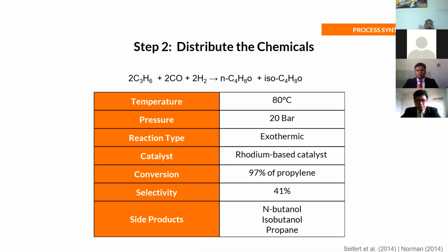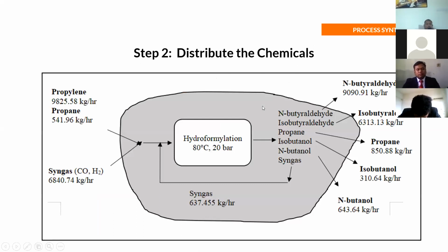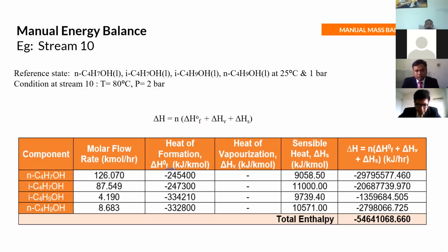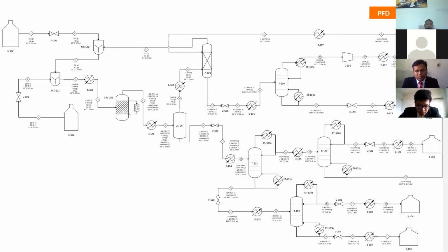Okay, I have one question, just a short question. Stream 22 and 23, please refer to your PFD. Actually, stream 22 is liquid phase, right? And there's a liquid and gas component. Why do you have to increase the temperature and then suddenly separate by using distillation? Why do you have to use distillation since the component is already liquid and gas?